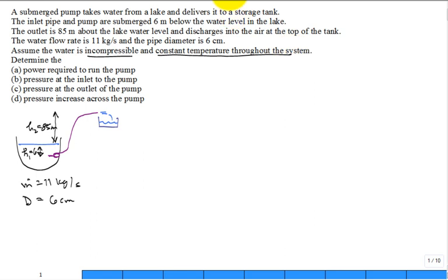So a number of people said, well, I'm going to draw a tight control volume around that pump. The inlet to the pump, I'm going to cut. I'm going to come around the pump, and the outlet to the pump. That's my control volume. A number of people did that. And then it's really just like what we did. We just focused only on the pump without any piping system.